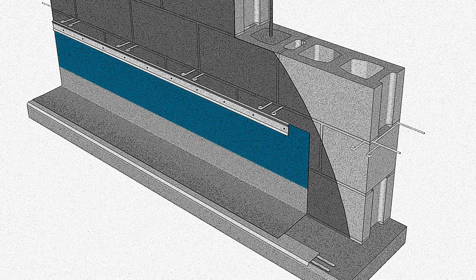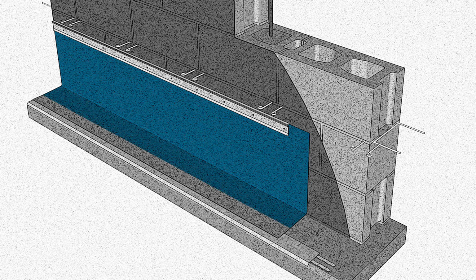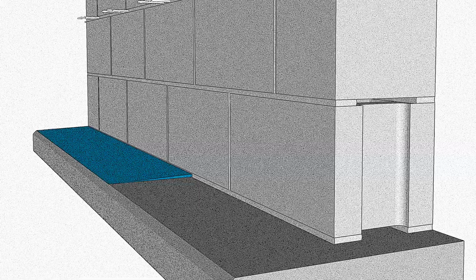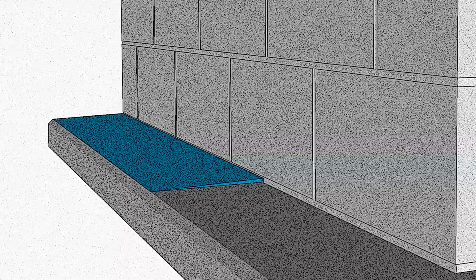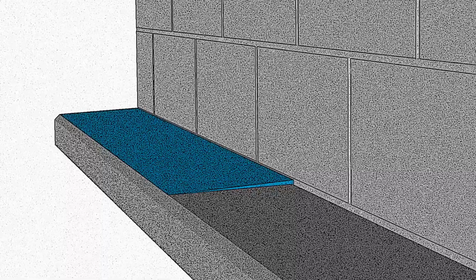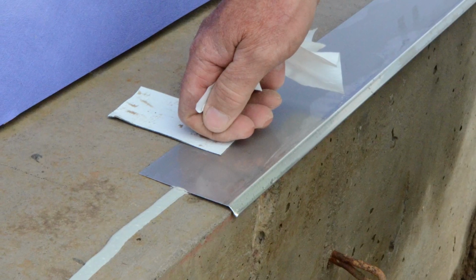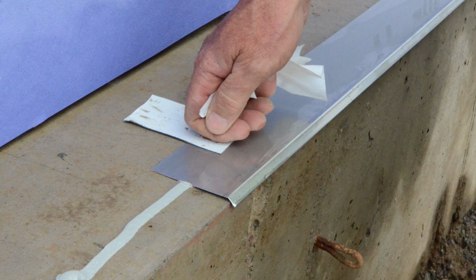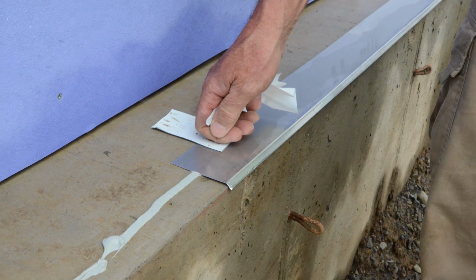The flashing should project downward along the outer surface of the inner width and then project outward at the masonry bed joint, shelf angle, or lintel to discharge moisture. Every effort should be made to slope the flashing towards the exterior. Effectively placed mortar or sealant material can help promote this drainage. The flashing should continue beyond the exterior face of the masonry a minimum of 1/4 inch and terminate with a sloped drip edge.